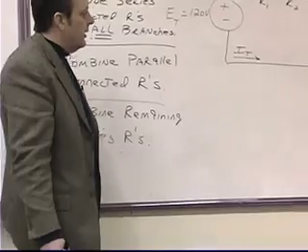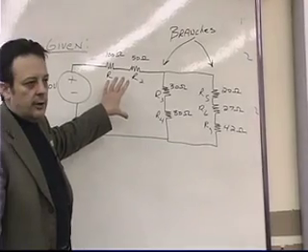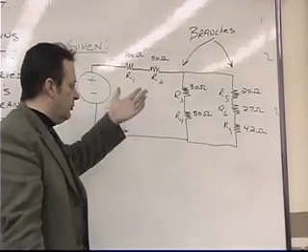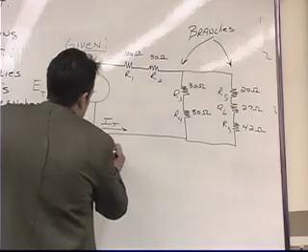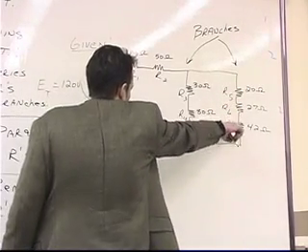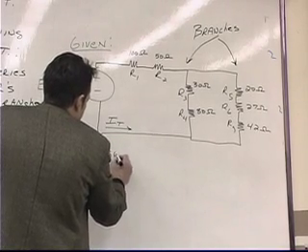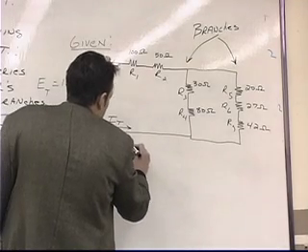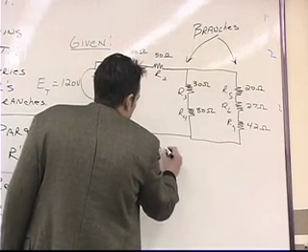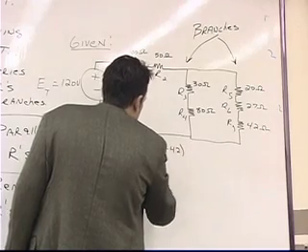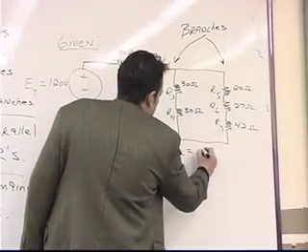So ultimately what we're going to end up with is a circuit that has a battery and one resistor. Okay? So let's go ahead and do that for this particular circuit. If we were to find the series total of R5 through R7, we could designate that as R5,6,7, and that would be equal to the algebraic sum of the resistors. So that'd be 20 ohms plus 27 ohms plus 42 ohms, and that would be equal to how many ohms? That would be equal to 89 ohms.